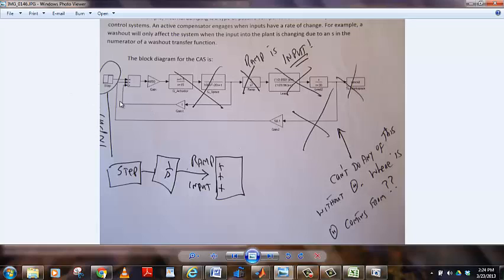Here's where the gyro output comes in. Here's where our input comes in from the stick or from an electrical command. We generate an error signal. The error signal goes through some compensation that we've built into an actuator and supposedly a time delay to operate the plant.